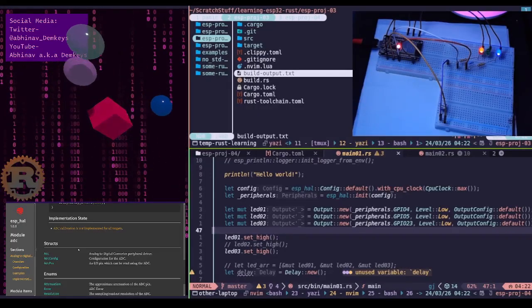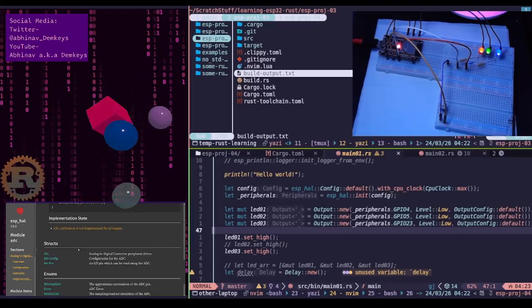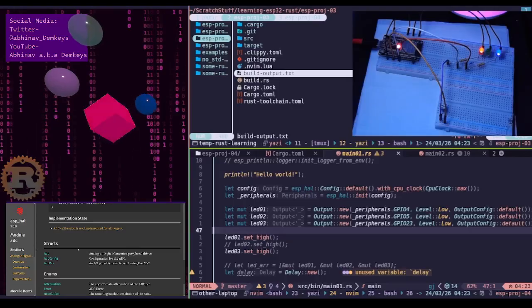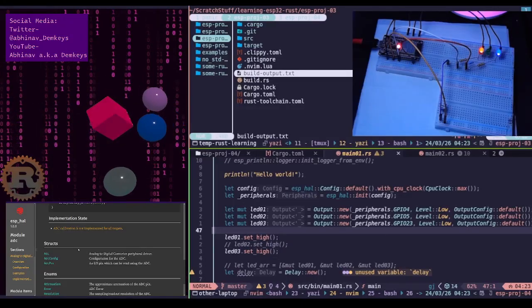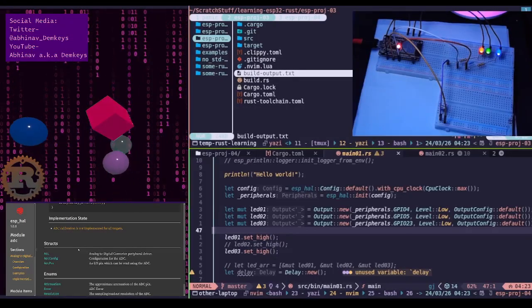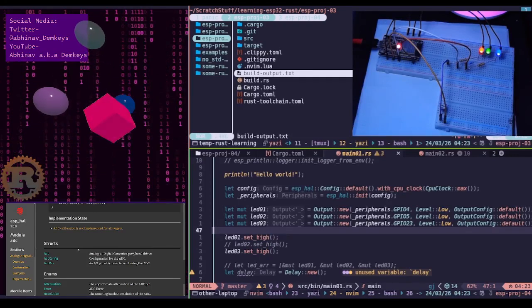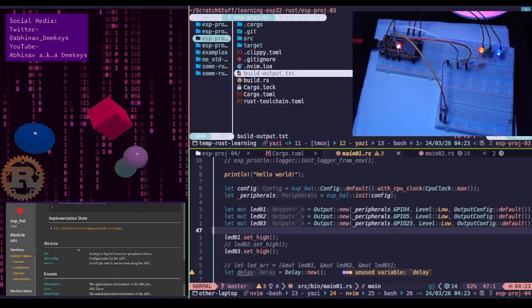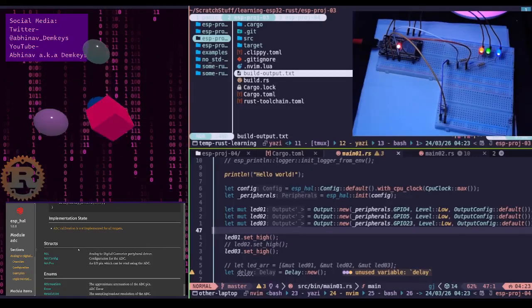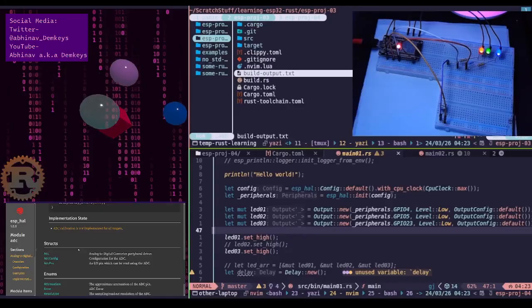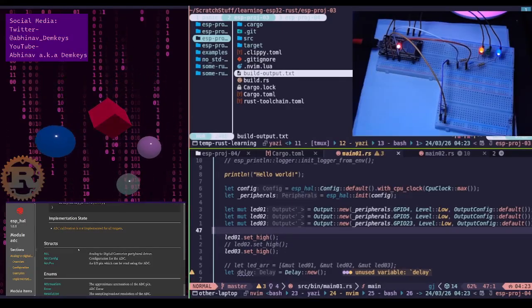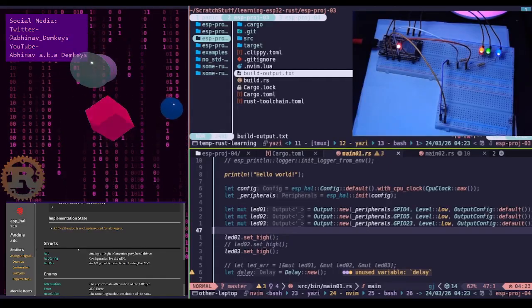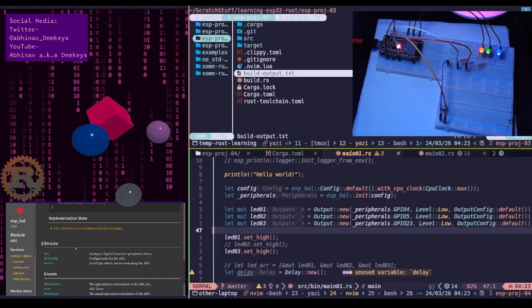Why would you want fewer bits? Lower resolution can sometimes be slightly faster to read, and it naturally acts as a filter for tiny amounts of electrical noise. If you only care about whether a dial is at low, medium, or high, then 9-bit is much easier to handle than 12-bit. True, true. The effective range. Wait, okay, so what I'm getting here is that the range would be 12-bit, but you can configure it to be lower.